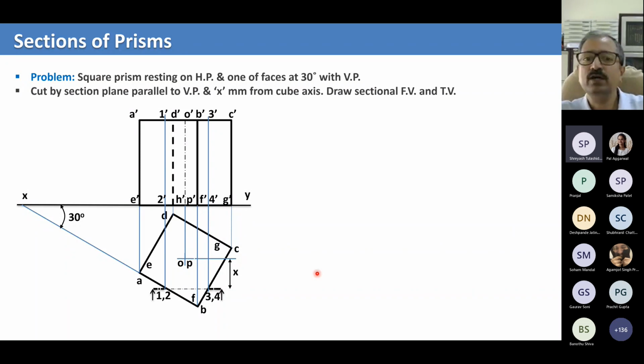To draw the cross-section view, you have to draw all the things by the way. So let me give you maybe 1 minute to do this, and it doesn't have to be measured. Just quickly draw by hand. Don't even use a scale and things like that. Just with your hand, draw your outer thing. Of course, first you draw the top view, ABCD, then you project it, draw the front view, and then you draw the cross-sectional. Do it quickly, 1 minute maximum.